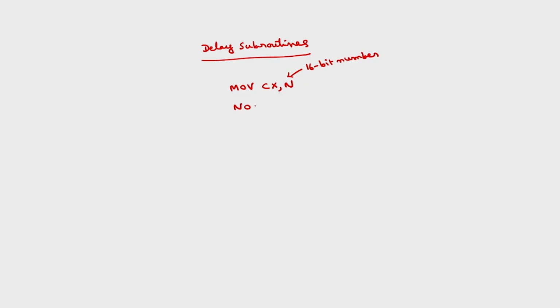You perform some NOP. So basically it does not perform any operation, as I have told while discussing the instruction set. This simply provides some delay. Then LOOP up, up will be here. After that, of course, the return instruction will be there, and the last instruction is return.